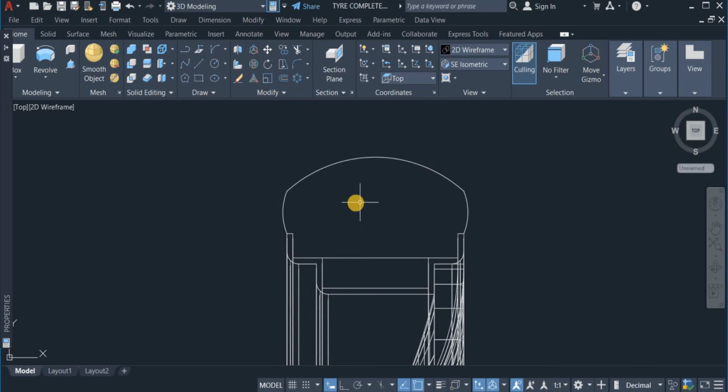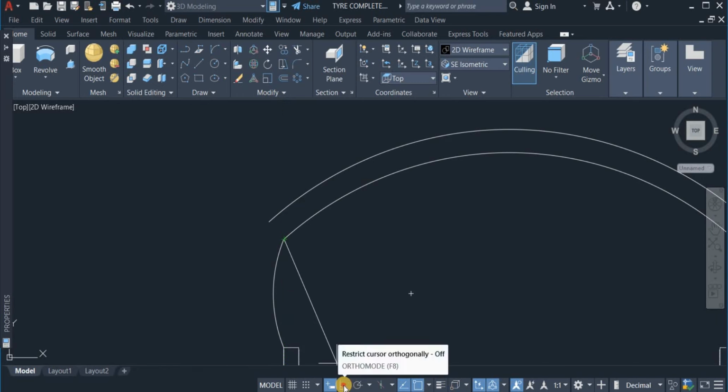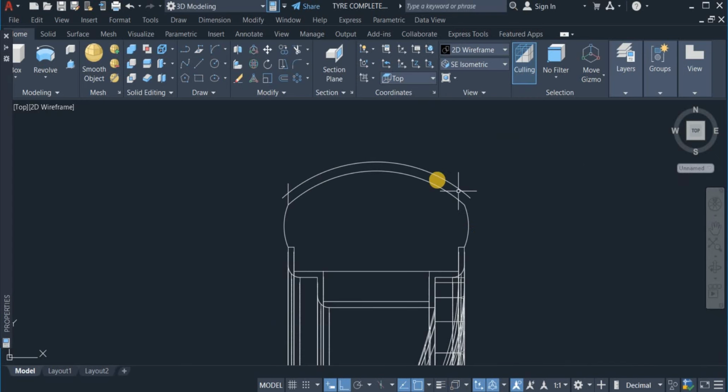Okay. So I'm now going to offset this very arc to a height of 15. So I'm going to use the offset command. Enter 15. Click on this. Okay, that's alright. Now draw another line from this point to cut through this. I'm going to check the auto mode here. Okay. Draw the same thing here, repeat line. Draw a line from this very point to cut this.